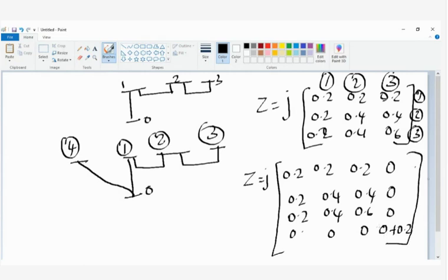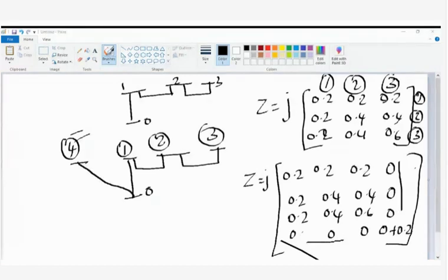Also think about it from a physical significance point of view. If you are taking the Thevenin equivalent at node 4, there is no connection between this node and any other node. So the Thevenin equivalent will be whatever is the shunt at node number 4. For any current injected at 4, there is no physical connection to 1, 2, and 3. It is connected via ground, whose voltage is 0, so there won't be any impact. That's why the off-diagonal elements for that are 0. Is it clear now?